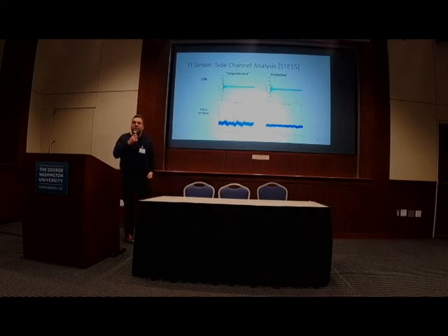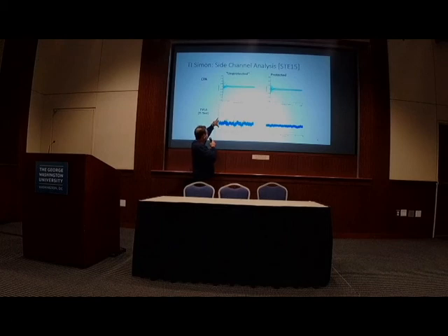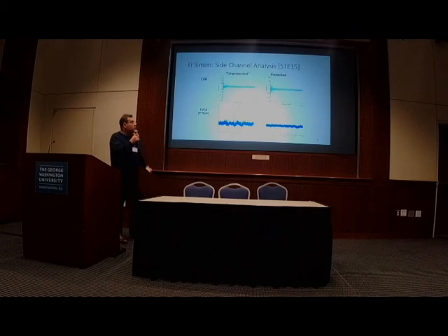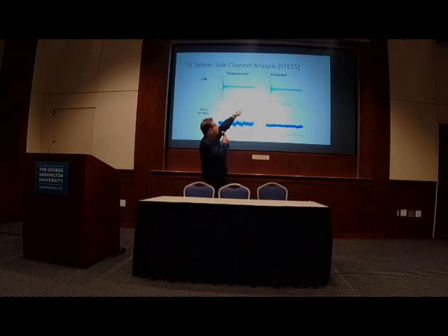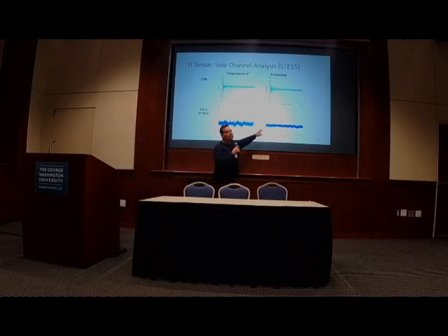It's a statistical technique that's used. And you see beyond 4, a p-value of 4, you have the leakage appearing. Then here's a protected implementation using a threshold implementation, and the red curve is contained within the traces in the ensemble, right? And you see the test also fails here. It's a nice demonstration. Very recent, actually, 2015 results.